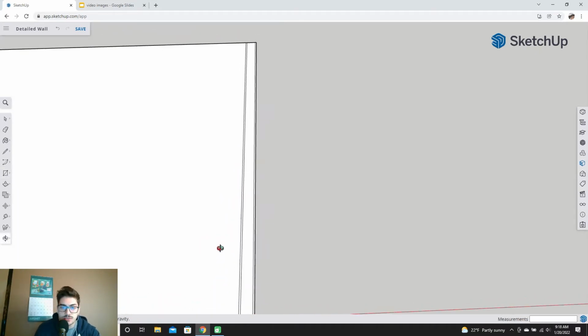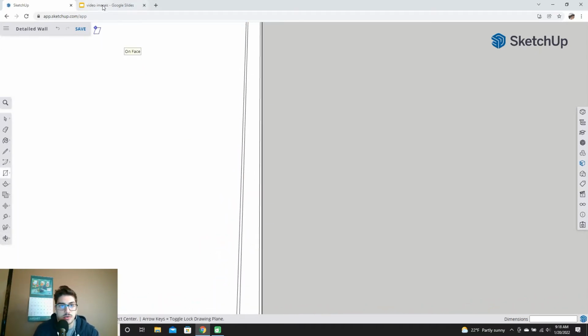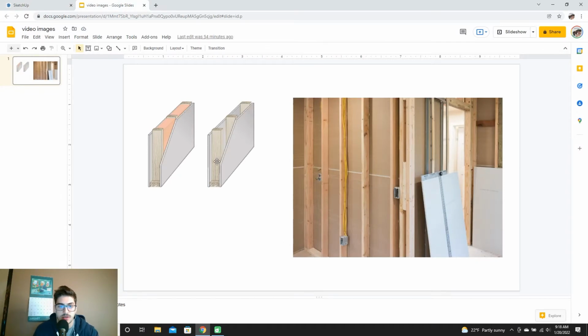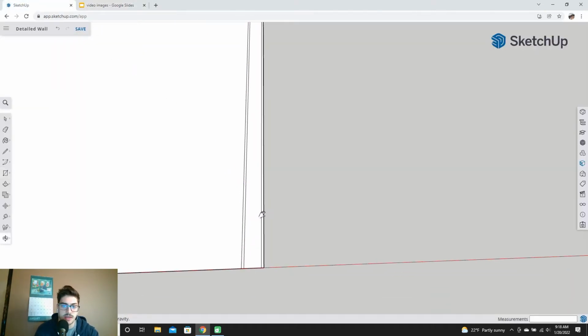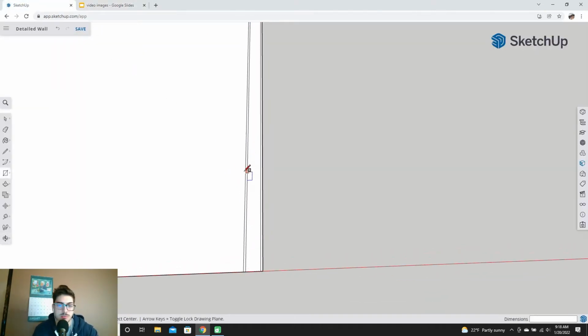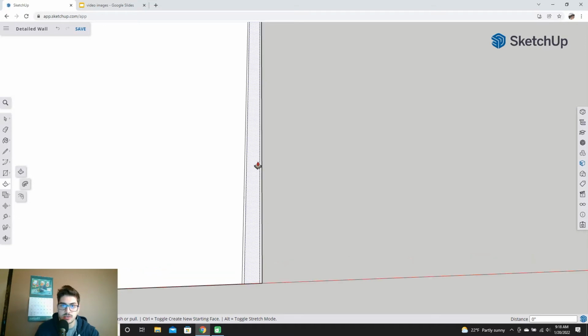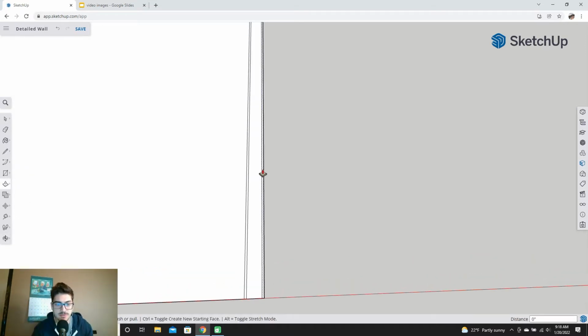But okay, so this kind of drywall sandwich, which again, going back to the images, is what you have here. That's what almost every interior wall has: 1/2-inch drywall, 3.5 inches of wood, and then another 1/2-inch drywall. And so we're going to start bringing this into 3 dimensions. We're going to ignore the drywall for now. I just wanted it to be there to be clear that if you're trying to get down to 1/2-inch sizing analysis to make sure things are going to fit, wiring runs, piping, anything like that, be sure to include the drywall because it's there.